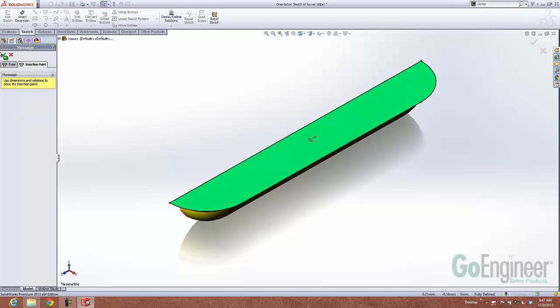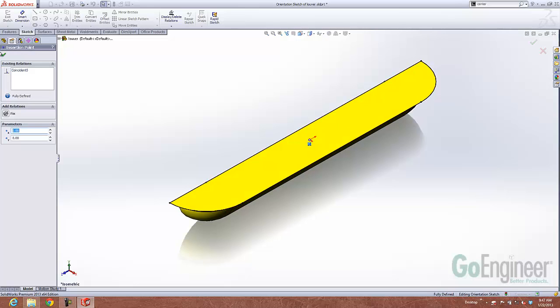This is real handy, not just for inserting the parts, but if your sheet metal manufacturer says, well, we calculate the center point or the dimension for the form tool at a different location, say maybe in the bottom left hand corner, you can select that guy here and move him over here into the corner, and then when you place it, they will be placing it by that corner, plus when you do your dimensioning, you can dimension to that point, and when you create your drawing, you don't have to make changes to your dimensioning values. It will just be there for you.